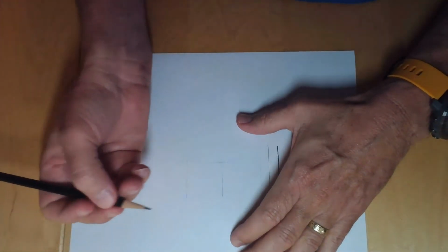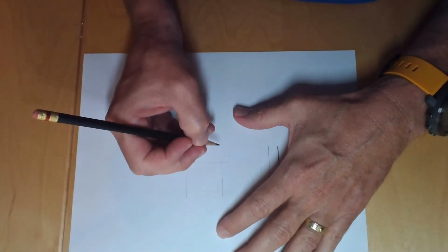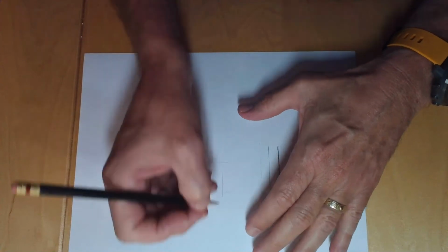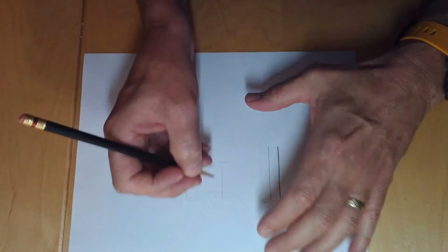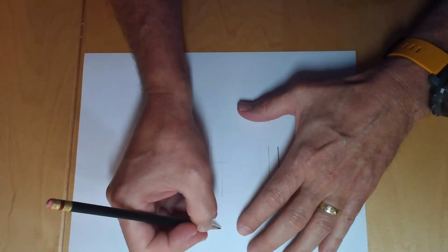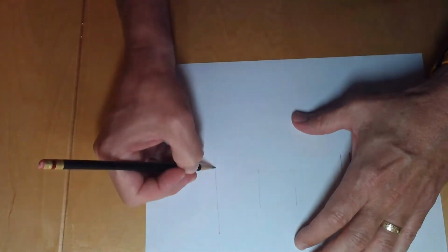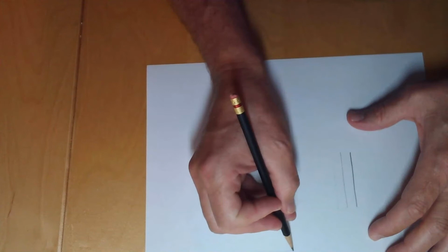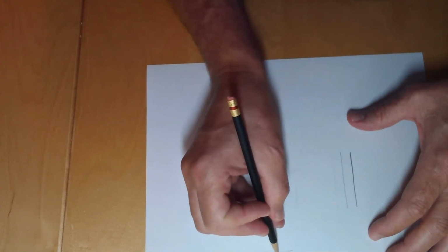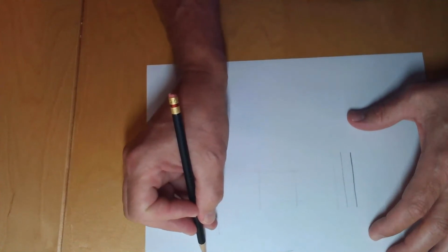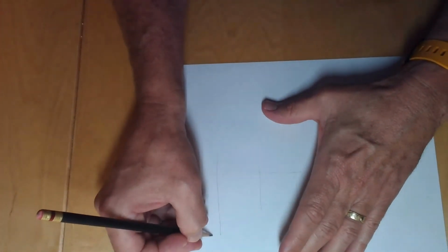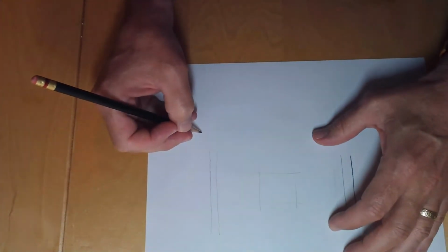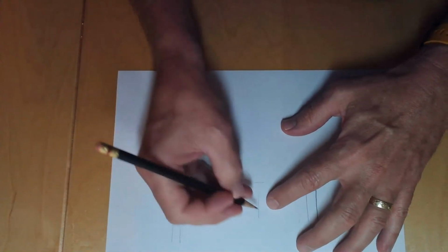So here is where I want to make sure I use the correct technique. What I like to do is use a pulling technique. In other words, the way your arm and your body work, it's a lot easier for you to draw a straight line like this than it is like this. When you're going like this, you'll notice that we have a pivot point in our shoulder and our elbow. So it's something that we have to constantly work on, to keep that straight. But when we're pulling, it's a lot easier to keep the line straight. So that's what I'm going to be working on here now when I darken this in.